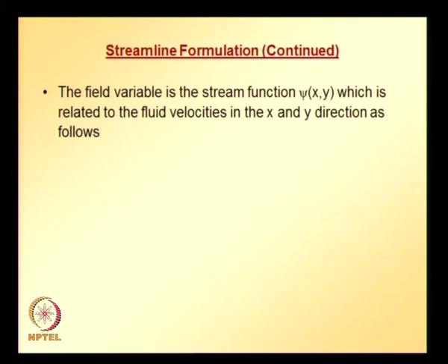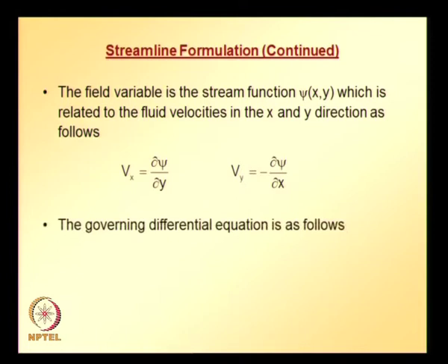So, the fluid velocities in x and y directions are related to the stream function psi, which is a function of x and y, through these equations. The velocity in the x direction is the partial derivative of psi with respect to y. The fluid velocity in y direction is equal to minus the partial derivative of the stream function with respect to x, and the governing differential equation is as follows.